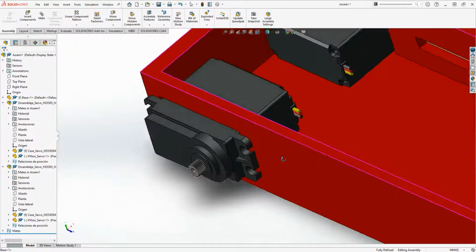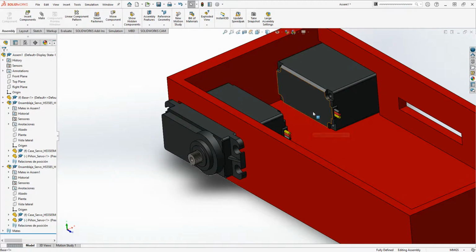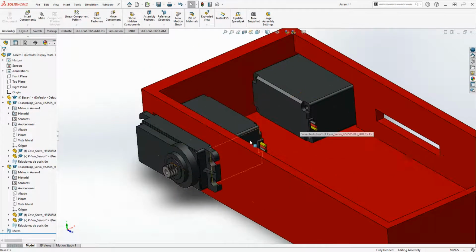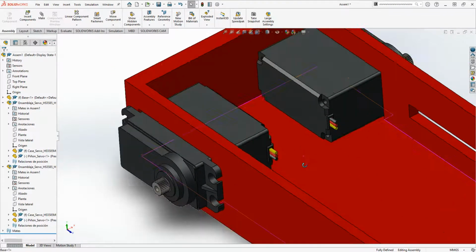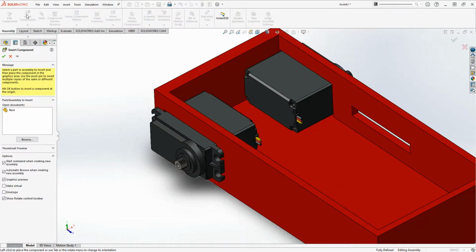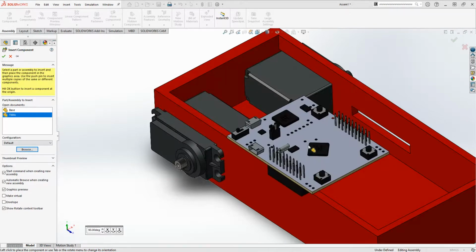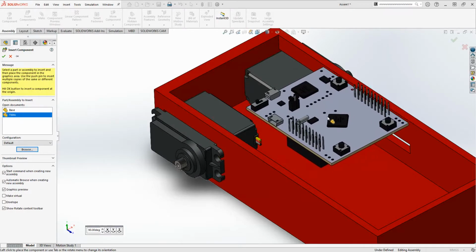And that's the big thing, because even though you would think, if say the servo motor is 15 by 30 millimeters, and I made the slot 30 by 15 millimeters, it would be such a tight fit that you actually wouldn't be able to fit it in. So it's important that you account for a little bit of extra room whenever you have in-slotted components like this. Just something to be aware of.